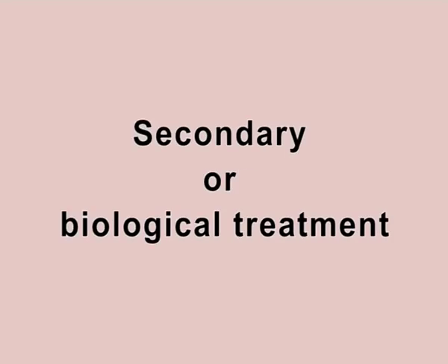The secondary treatment, which is generally called the biological treatment process, includes aerobic and anaerobic degradation of the waste in the liquid. In several countries, most of the food processing plants deliver their wastewater to municipal systems after primary treatment. But in some cases, the wastewaters may pass through a secondary biological treatment, which includes aerobic and anaerobic processes. In fact, to complete the treatment of the food processing wastewaters, the waste stream must be further processed by